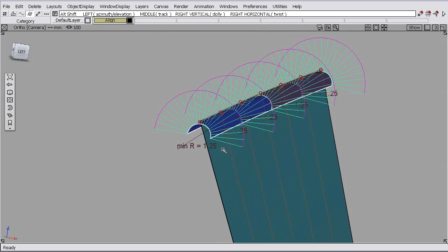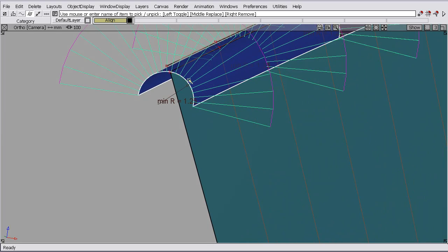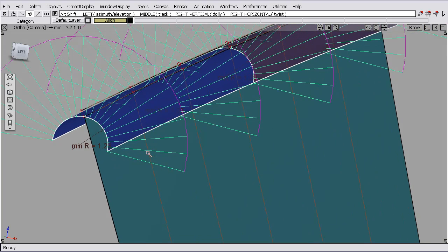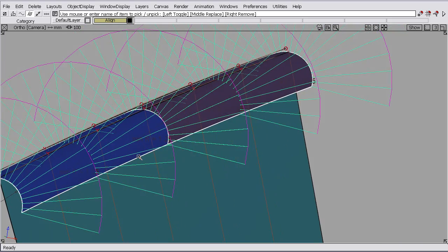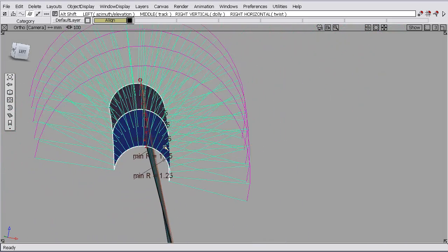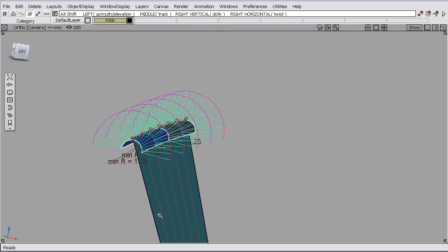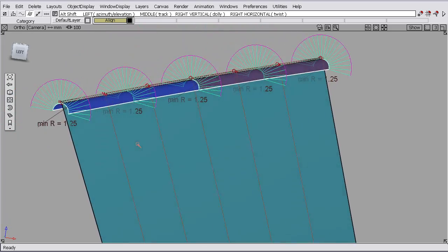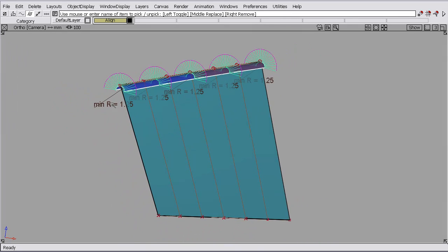So I was not allowed to move this curve or this fillet. So what that meant was I need to find the place around this fillet where it points down at that curve and is tangent. And I need to find that at every point along this three-dimensional shape. So it's not planar in either view, or any view. To do that, I'll show you how you can use the align to help solve that. Now, I know this appears to be a little bit of an obscure situation, but it's some methods that you can use, and you'll need to apply these to your own surface design scenarios.